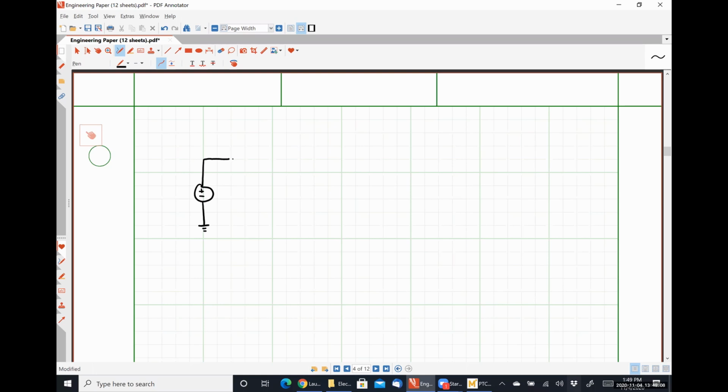Let's see, that was a resistor, so it's going to stay a resistor. That was my 73 ohm resistor. Then I'm going to have a voltage source, positive polarity terminal on the left, because the head of that arrow was on the left, in series with my capacitor, whose impedance I don't remember off the top of my head, so we'll get that in a second.